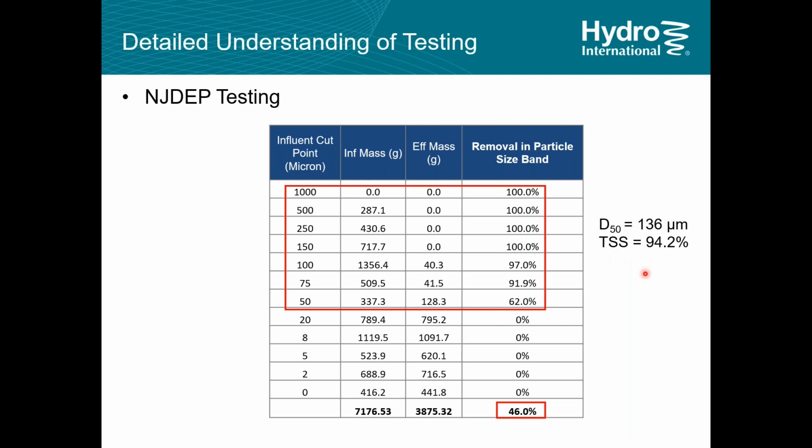So you need to understand what's behind the testing protocols, the particle size distribution, because when you look at a separator, this stuff below about 50 microns is filtration material. You're not going to get it with a separator anyway. So to include it as part of the test is like asking it to do something it was never designed to do, and it falsely limits the equipment by saying, well, you didn't get this, so you only get that score.